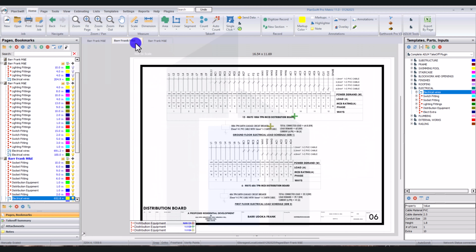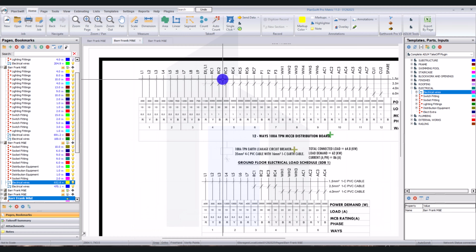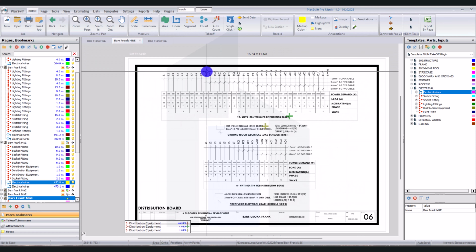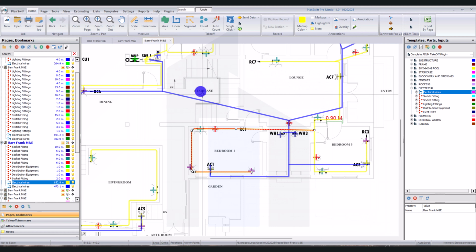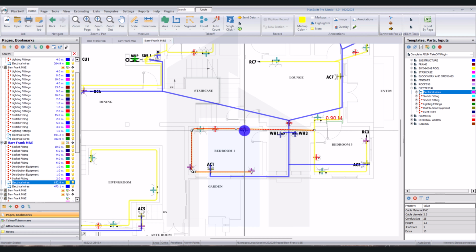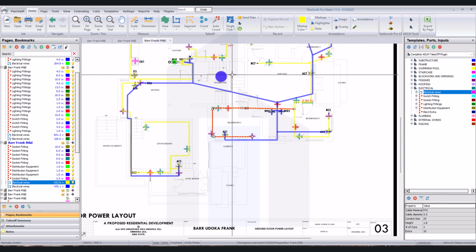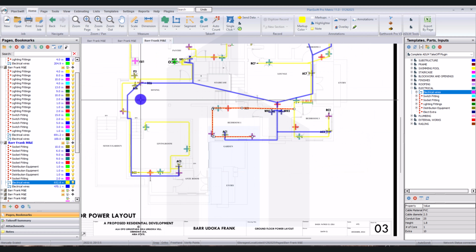You see we're done with this lighting circuit. So we have the next circuit, which is this exterior light circuit, also EXL. That's exterior lights. Exterior light is also in the 2.5 cable range. RC1 down to RP3, they are all 2.5 cable. So what you do is check out your layout. This is the RC circuit, RC1, RC7, RP3.